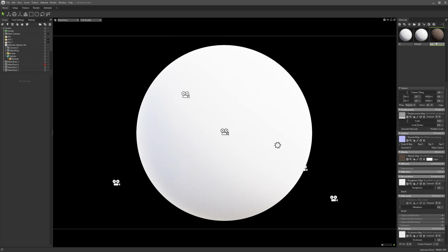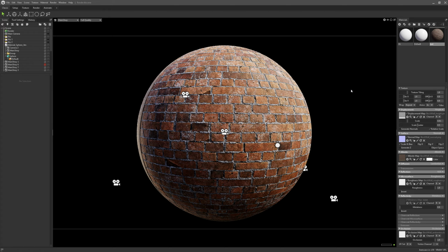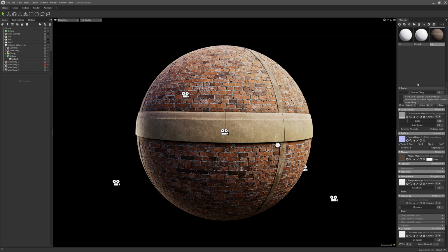You can see it right here, but there are some things missing and I can see it from the preview. So I'm going to drop my material here onto my sphere and it's going to load. As you can see, my material is there, it's ready and working, but there are some things that are not working well. First, it's not showing all of my material, so I'm going to change this tiling to 2. That should start showing everything of my material.